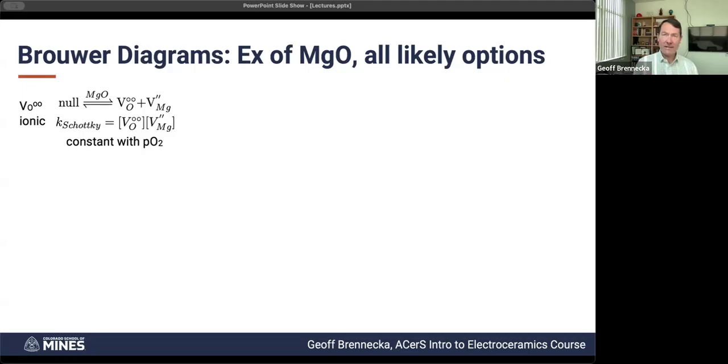So if those pores that you're talking about are open to the atmosphere, then that becomes a little bit more difficult, because there might actually be reactions happening, just like we saw in the reactions with oxygen vacancies and oxygen gas coming and going. So if it's a non-reactive gas, like let's say you've got an alumina that you're sintering in nitrogen, and it's not a low enough PO2 that you're actually pulling oxygen out.